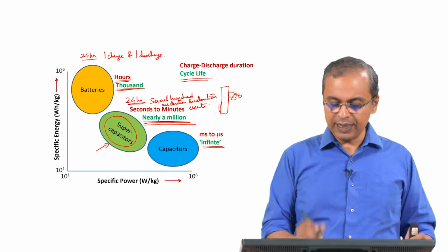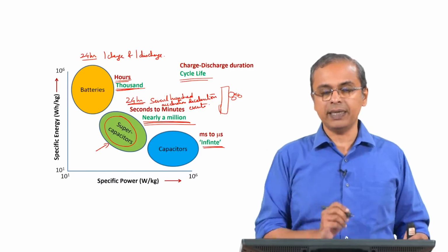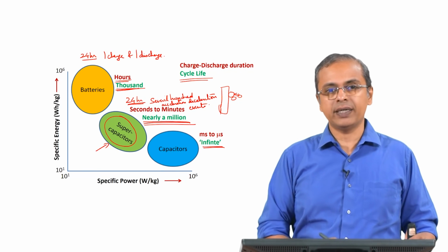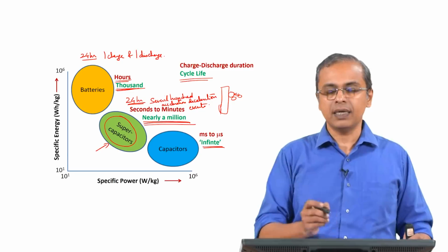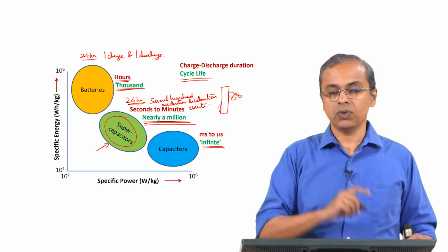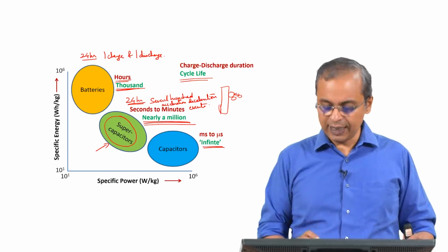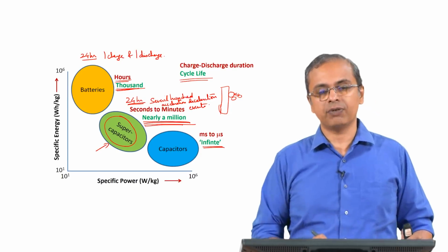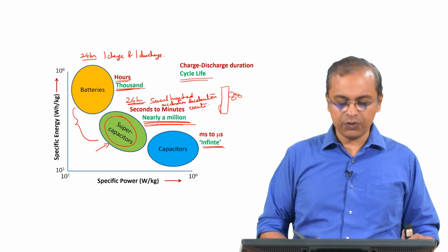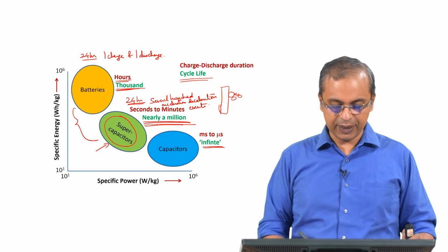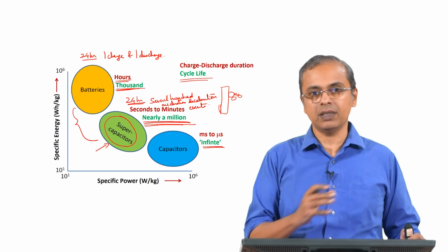But a million times charge and discharge ability, 3 orders of magnitude more, becomes necessary, because you may in fact use it a few hundred times each day. So, you will have to multiply it by a few hundred, and then the million really works out comfortably for you. So, that is how these two taken together, the battery supercapacitor combination, are really useful for electric vehicle applications.